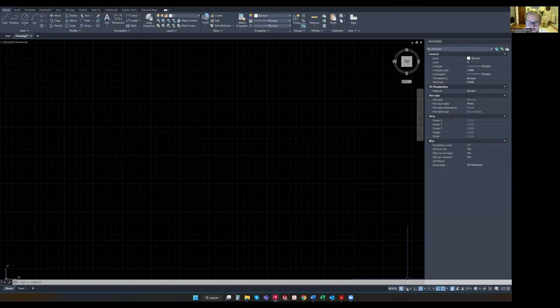And there is an option actually, if you turn this snap mode on right here, these little dots, this turns your grid on and off. This right here makes it so that you can snap to your grid. Right now we have it set to only snap to the bold lines.